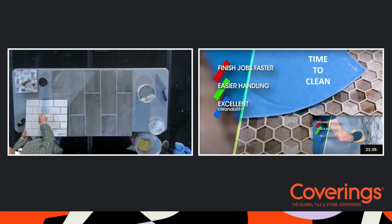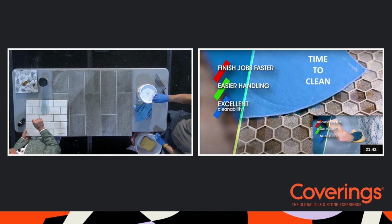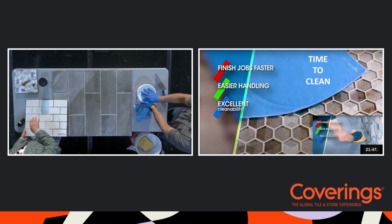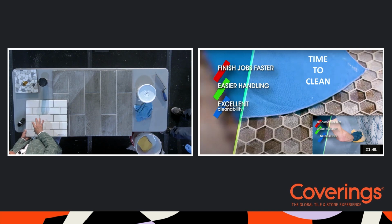And I assure you, doing a top grout is much easier to do than a color stain, 100%. Color stain was our previous solution. It's not now. This is much easier and gives much better performance as well, because a color seal can also degrade and require some maintenance. If you top grout with the Prism SCG, it won't degrade and it never requires a sealer. So excellent. If I have trade damage, because of those adhesive properties, a quick sponge wipe, fill it, sponge wipe, done. As soon as it dries, it'll match the color perfectly.